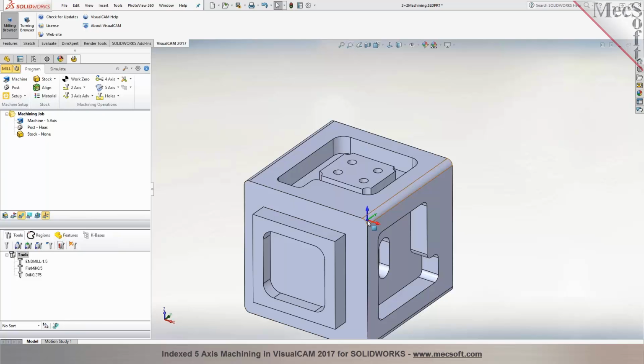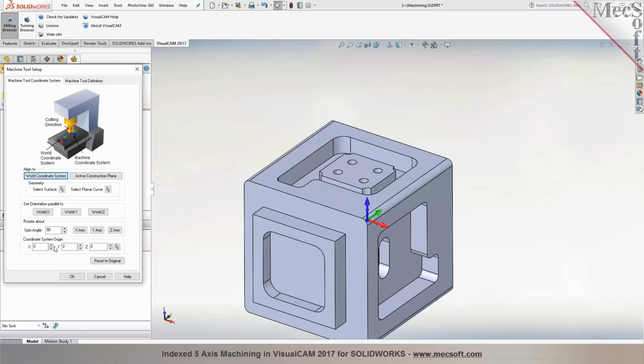Okay, by default, yes, and match it. Now, typically users may not be using this orientation or origin when they design the parts and create the drawings, because they're probably not taking into account how it's going to be machined, because the design engineer is not aware of how the CNC programmer or the user is going to machine it. So that's the reason why you have all of these nice controls in here to establish the orientation and also establish the origin.